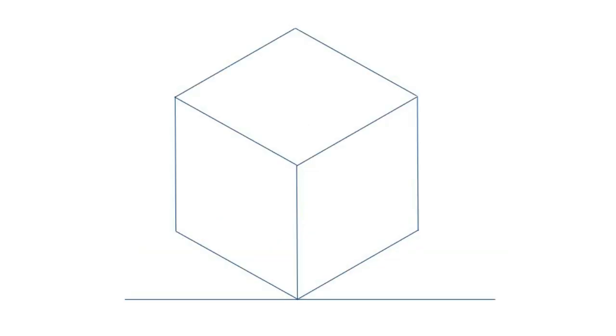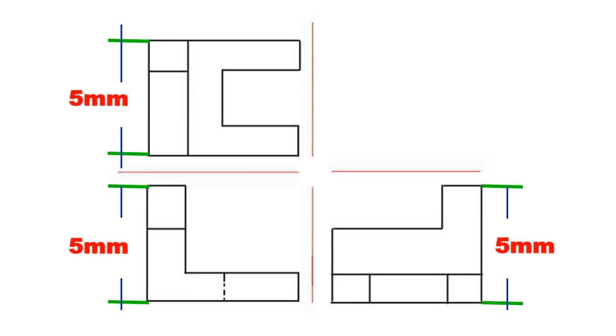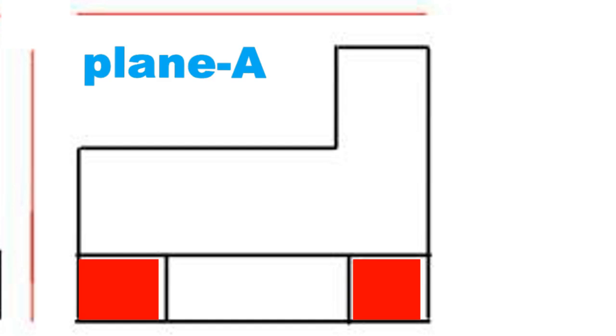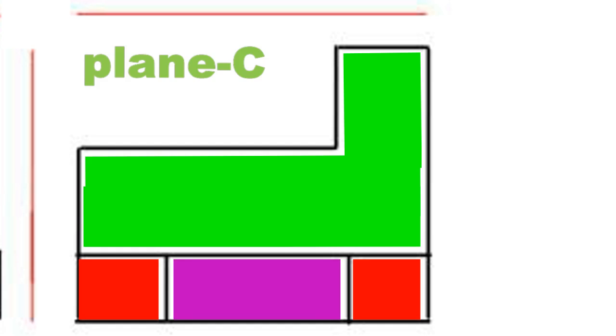We must construct a 3D orthographic view of the box after creating a 3D isometric box using the specified dimensions. The side planes are added to the 3D box step by step, and we expand them using the top and front side views. Thus, give plane names A, B, and C before drawing planes.